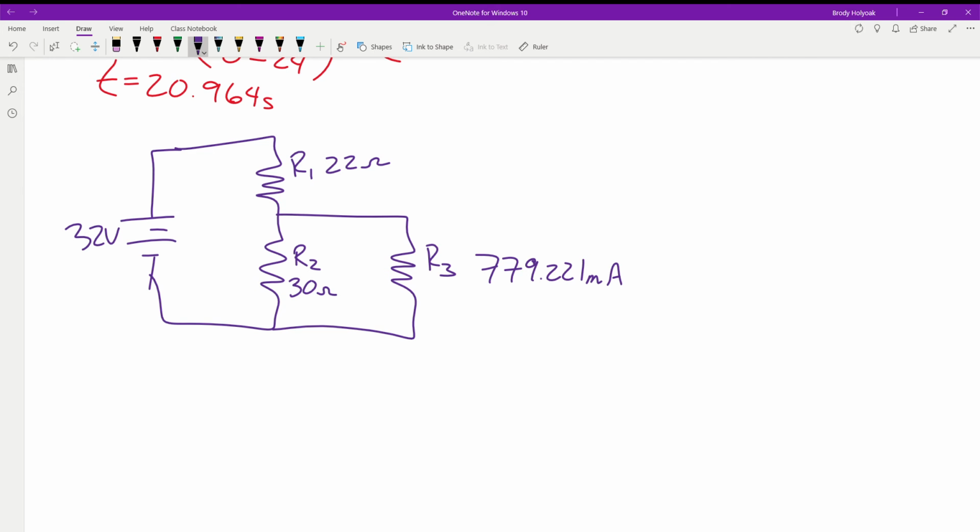So with this, we don't have any information. We're stuck on all of our options to go through these. We don't have another piece of the puzzle to solve for any of the voltages, total resistance, total current, anything like that. So at this point, the easiest thing to do is use Thevenin, because this allows us to remove something from the circuit and not worry about it until the end. That's one of the other ideas of Thevenin, it allows us to kind of cheat our circuit. Gets rid of something.